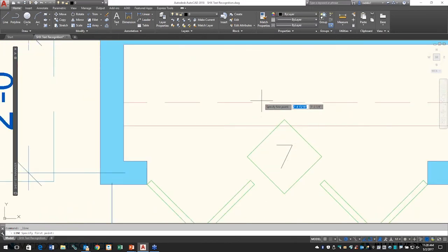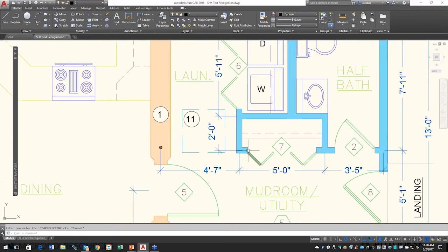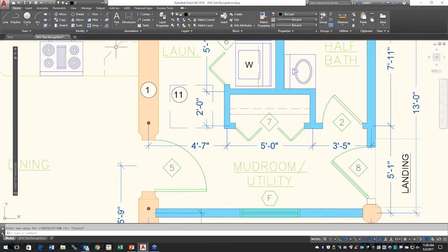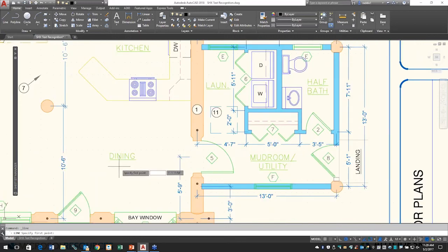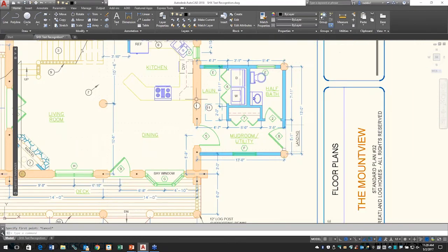let me work with the dashed line, it'll be a little bit easier to see. You can see I can snap to, as I come down, oh, let me see if my LT gap selection is on. LT gap selection set to 1, should be there. It should be taking me, let me go back to, yeah, it should be selecting that. It worked fine during demos. I'm not quite sure why it's not working right now, but you should be able to select to that particular gap. I'm failing terribly here at this point, but trust me, it normally will work just fine.